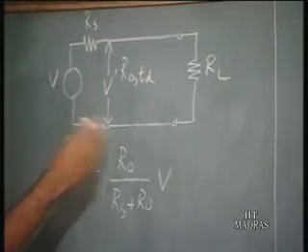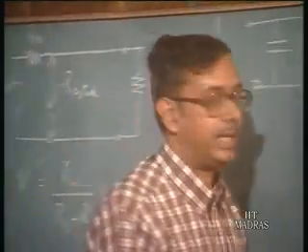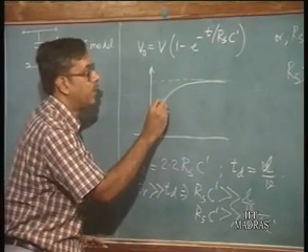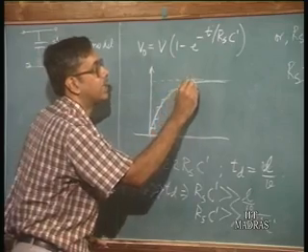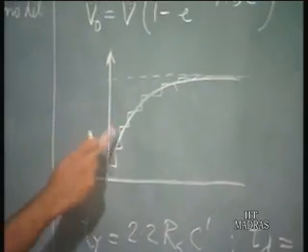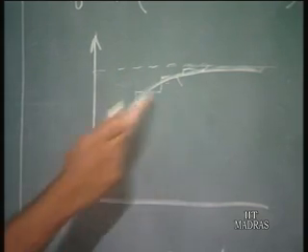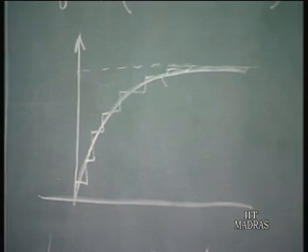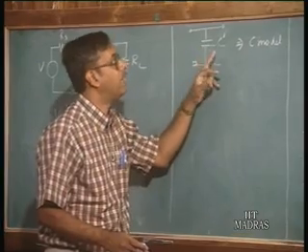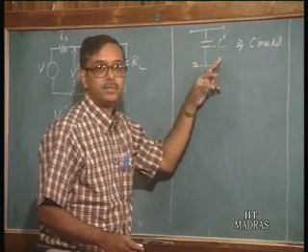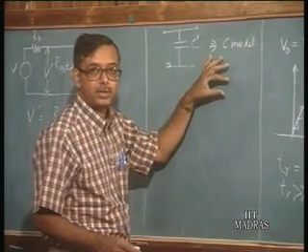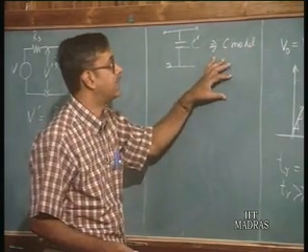when the multiple reflections take place. So if you do a transmission line analysis here, you have V prime coming here, and then it will go up. So you're going to have a situation like this. Transmission line analysis will give you something like this, whereas if you just replace the line by lumped capacitance, you get something like this. So the C model which we have here, that is, replacing the line by the capacitance, is valid when you have Rs very much greater than R naught, that is, the source resistance is very much greater than R naught.